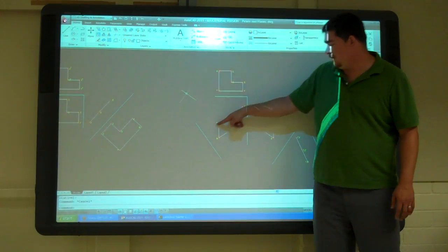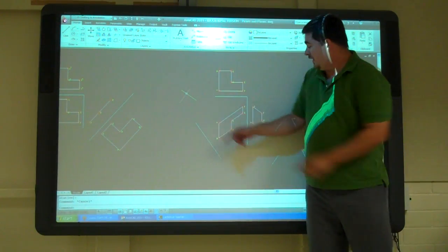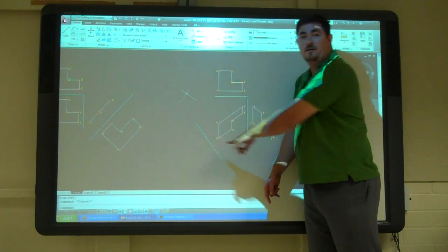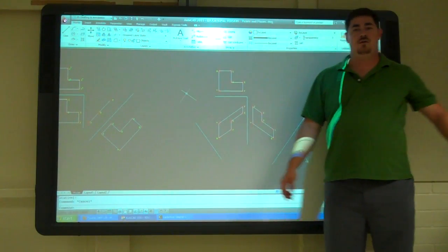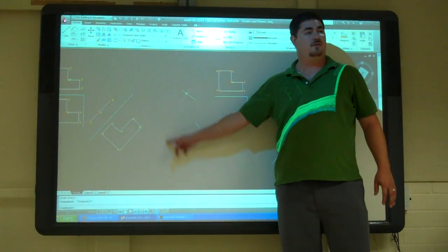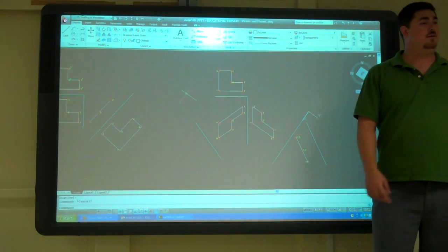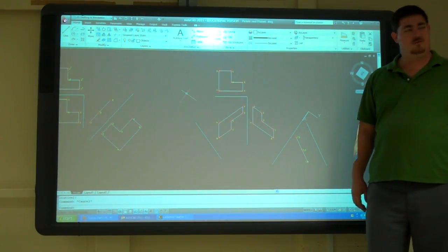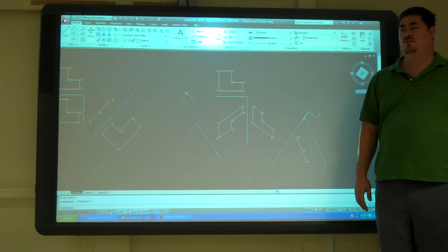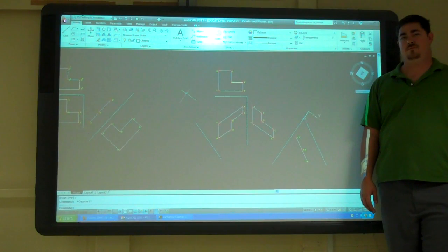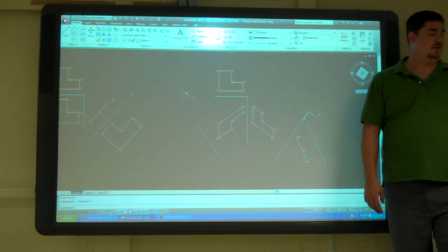So if I came perpendicular, made my folding line perpendicular to AF, now when I come off, AF are going to be 1 point, right? D and E will be 1 point, B and C will be a point. So this would give me an edge view too. So that would save me doing 1 view, right? Because that'd be 1 view closer. Instead of 5, you got 4. So, questions? All right.